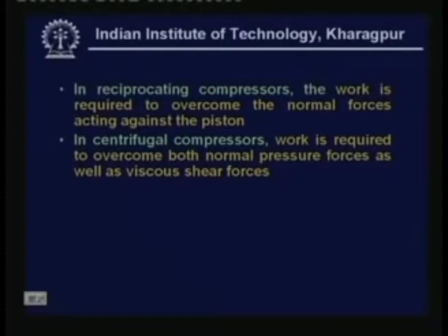Whereas in centrifugal compressors, work is required to overcome both normal pressure forces as well as viscous shear forces. Here the refrigerant has to flow against an increasing pressure, so you have a normal pressure acting on the refrigerant. In addition to that, it also has to overcome viscous shear forces. So the work input is required for these two purposes.